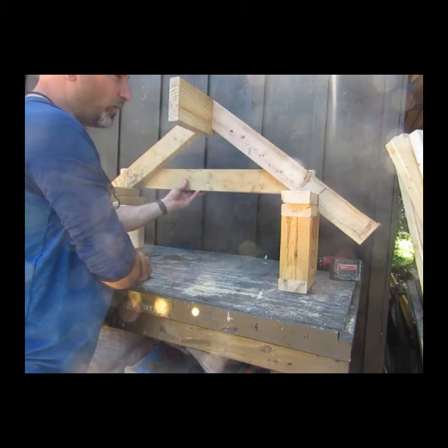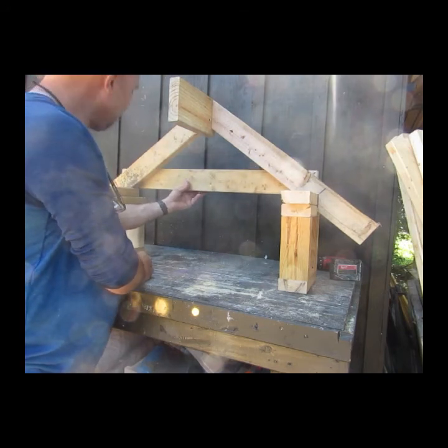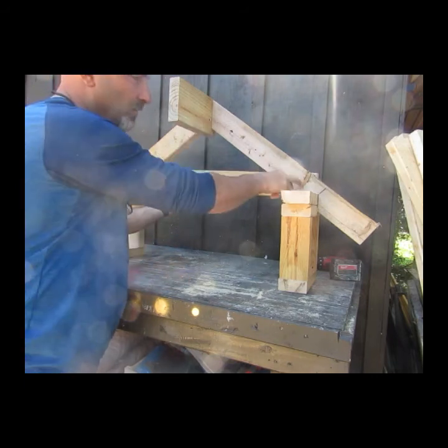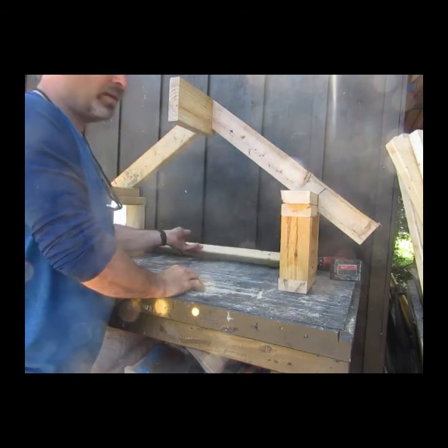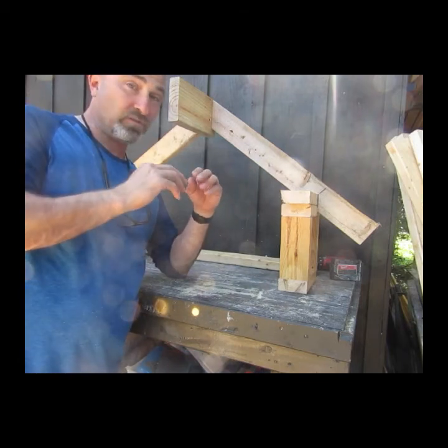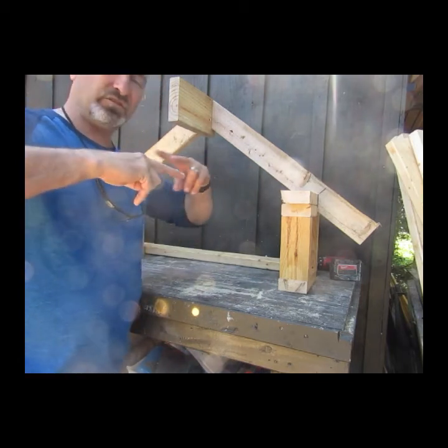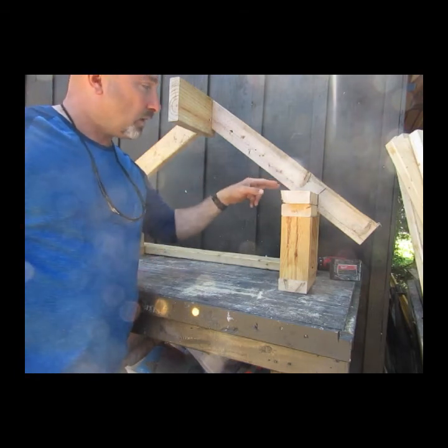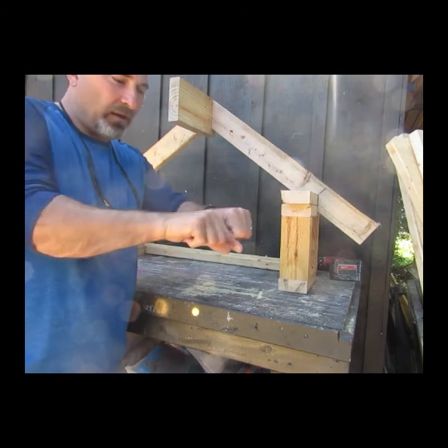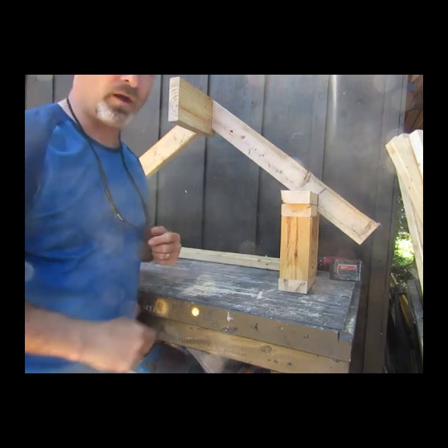But seeing as how where it's going to go, I think I'm just going to do a nice overlap of the wood, and then I drive nails in, maybe 4 nails each side. And again, those nails going in this way don't hold it together. All they do is hold the wood in place. They fasten the 2 pieces of wood together. The 4 galvanized Ardox nails of the correct size will resist being sheared apart.